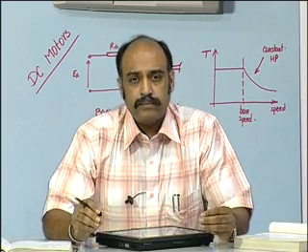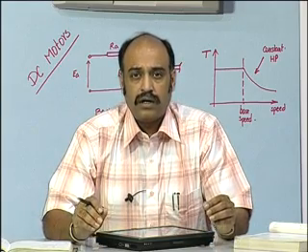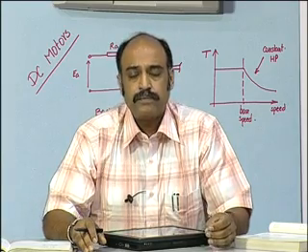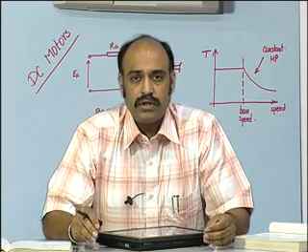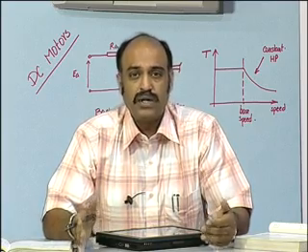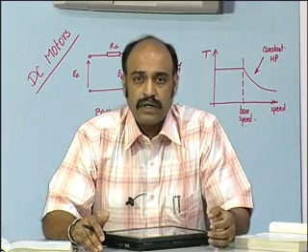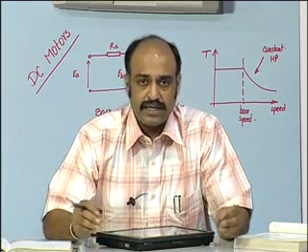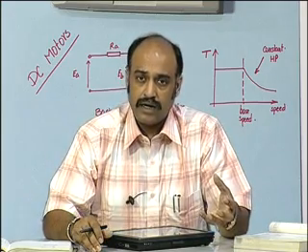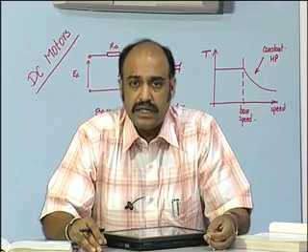All the equations and the principles involved are exactly similar to the case of the DC generator. The DC motor's back EMF, which is equivalent to the induced EMF in the case of the DC generator, in both the cases, that is the back EMF here and the generated EMF in the case of the generator, have the same equations, that is P N phi Z by 60 volts.